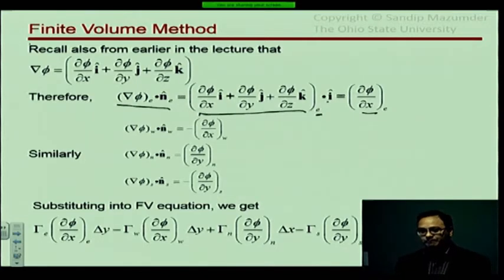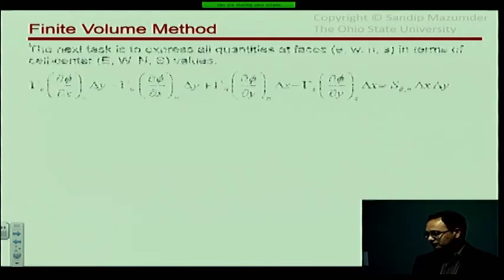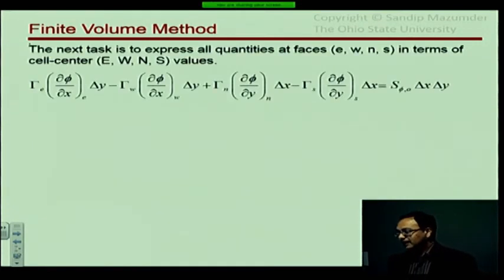Everybody follow that? All right. Next task is to express all these quantities at the faces. So these derivatives at the faces, in terms of the cell center values of phi at the east, west, north, and south locations.